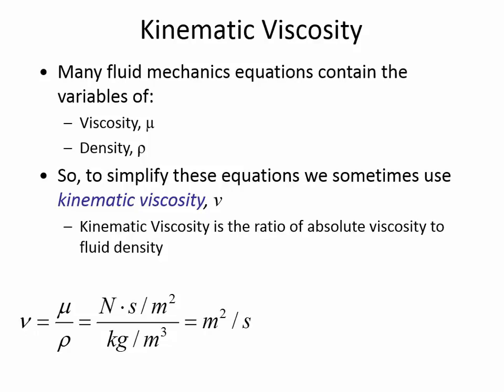As you might expect, fluids have their viscosity change dramatically as a function of temperature. Anybody here ever changed the oil in a car before? If you want to get it done quick, is it better to change the oil when it's cold or when it's hot? Hot. Why is that? It runs out of the pan a lot more quickly. Yeah. So increases in temperature increase the viscosity of gases, but decrease the viscosity of liquids. We'll see a graph of that in just a moment.